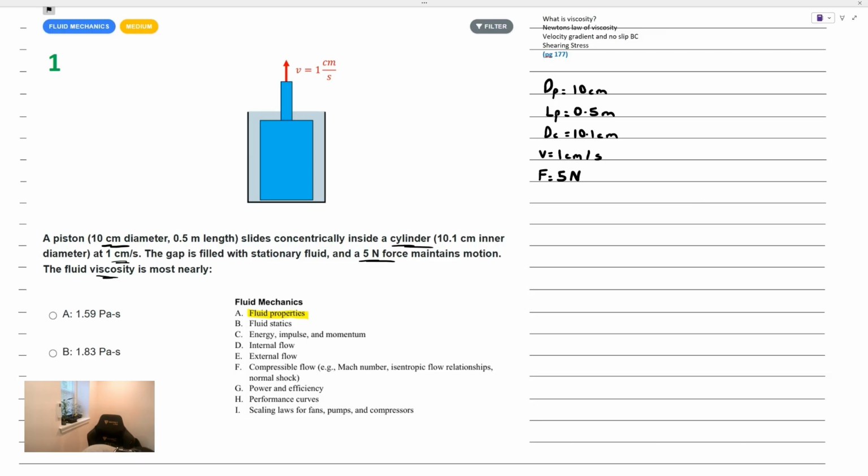There is the dynamic viscosity mu, that's the absolute, or the dynamic viscosity mu, and then there's the kinematic viscosity nu, that's equal to mu over rho. Now, the kinematic viscosity is called that way because there's speed inside of its units. The standard unit for the kinematic viscosity is meters squared per second. And you can kind of see there's a speed term of meters per second inside of that kinematic viscosity. So we call it kinematic because it's more focused on speed and not on forces.